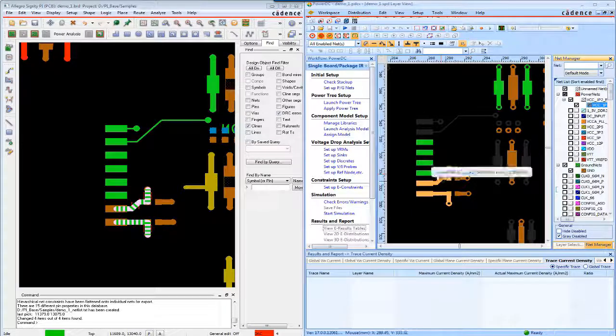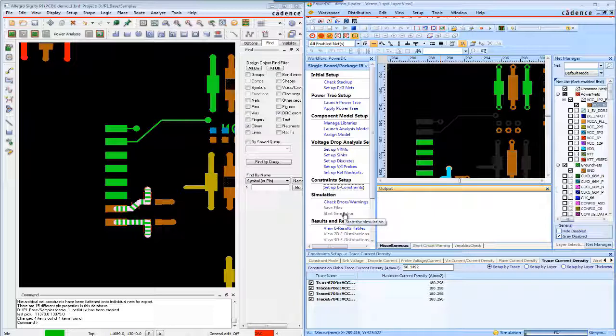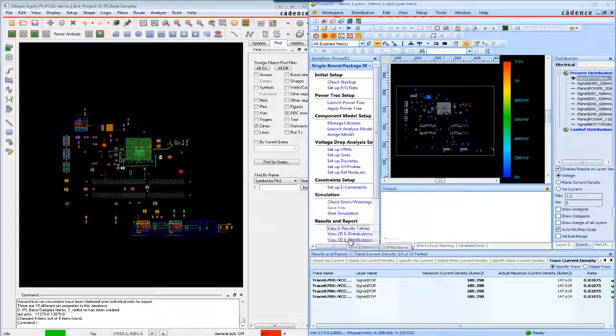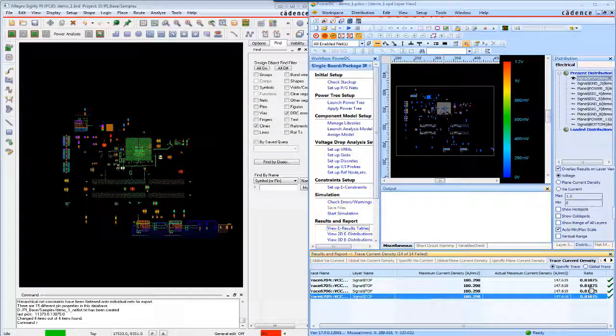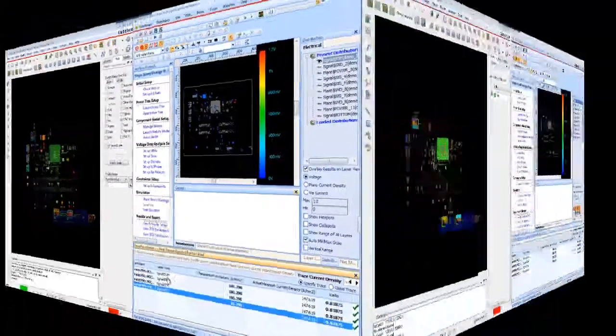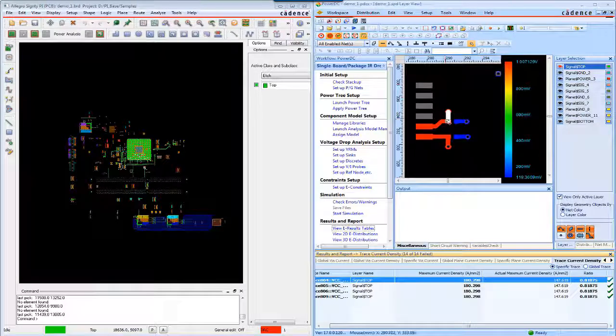You can see the traces have changed, and from the Constraints pane, we see the constraints still apply just like before. So let's rerun the simulation and see how it looks. And it's done. So looking at the results, we no longer see any violations. Our simple fix worked, and it was easy for the PCB designer to implement. The PCB designer can verify it's fixed for themselves too.